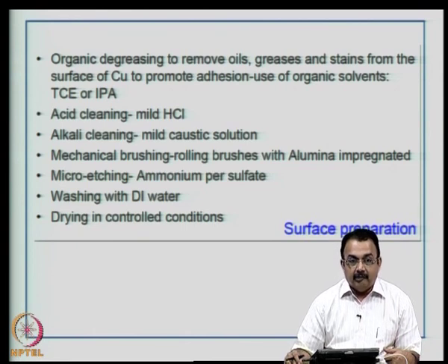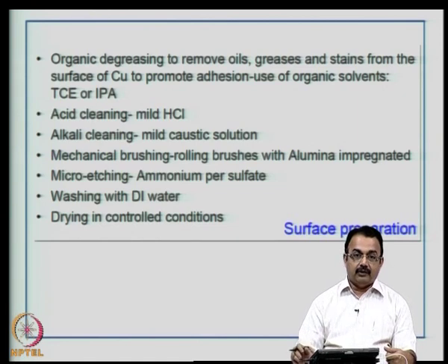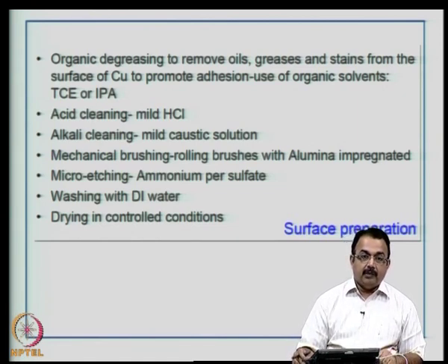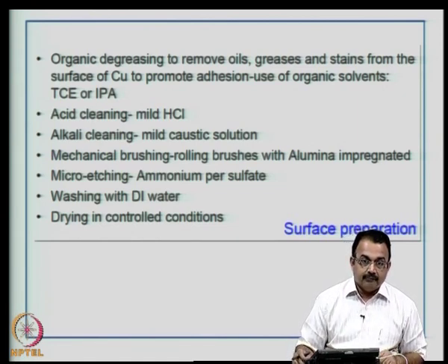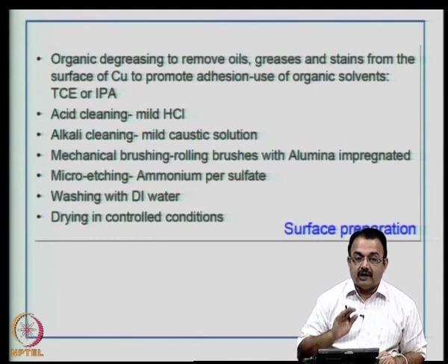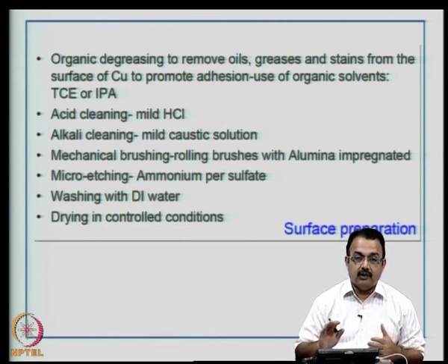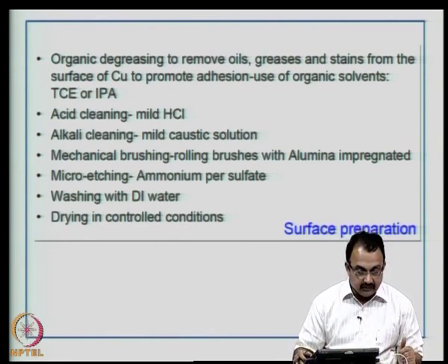Generally, laminates need to be protected until they are used, but if not, nevertheless you have to treat the surface of copper. Now, the treatment is required because we are going to promote adhesion on the surface of copper. How do we do that? As you know, you are now going to transfer an image onto the copper surface using a photoresist material. So, this photoresist has to adhere nicely onto the copper surface.